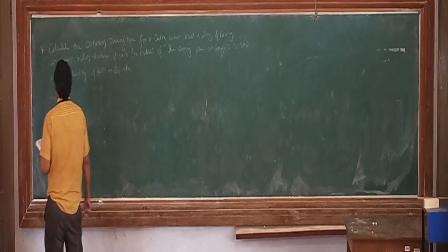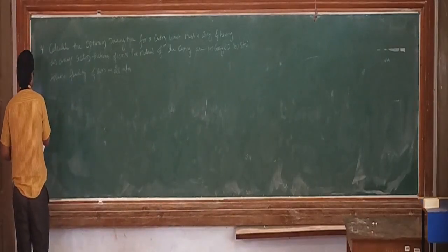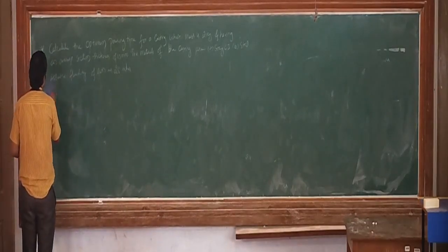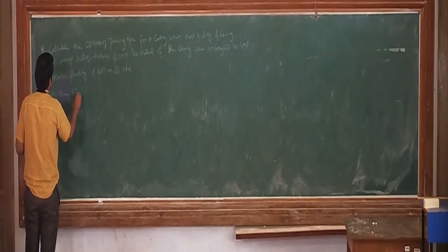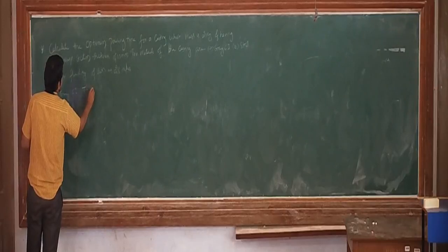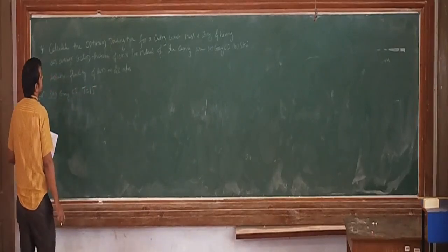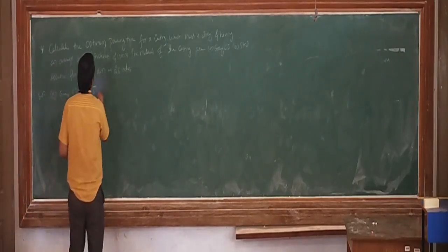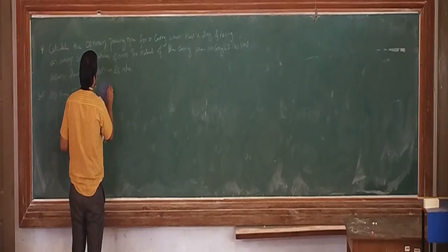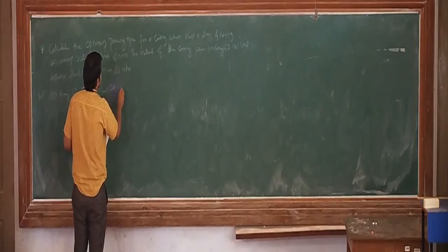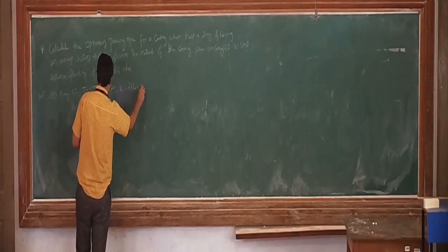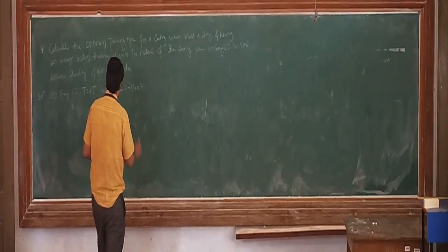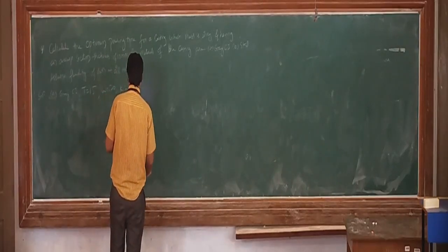Okay. Now we will first solve for grey cast iron. T is given as 15 millimeter. Weight of the casting is 20 kg, that is W. K we need to find out, 28 divided by 40. So we are going to just keep it as it is and substitute in the formula.